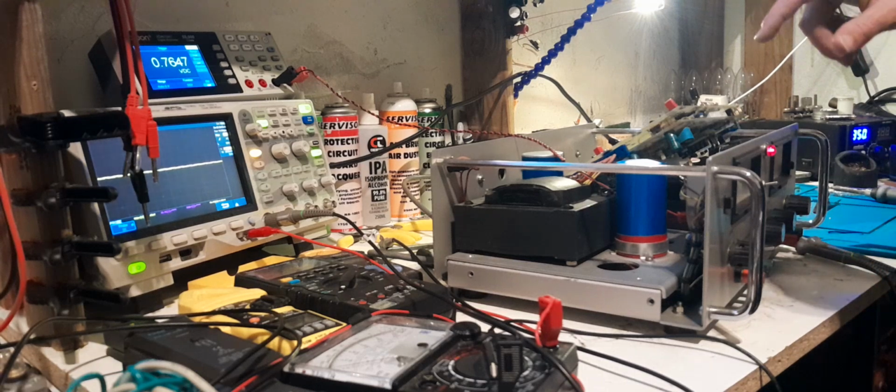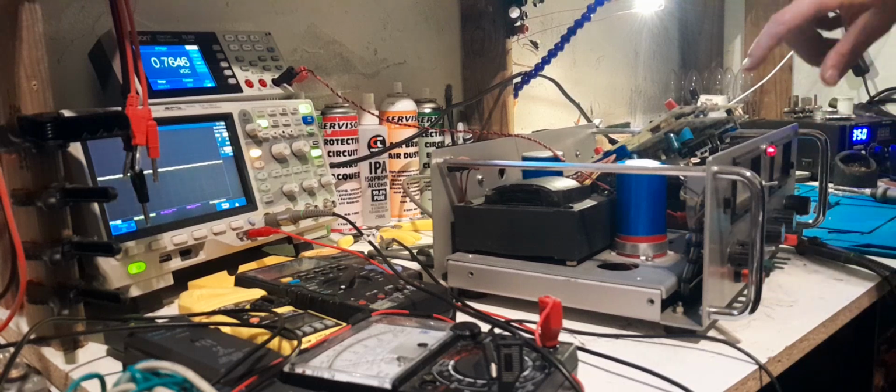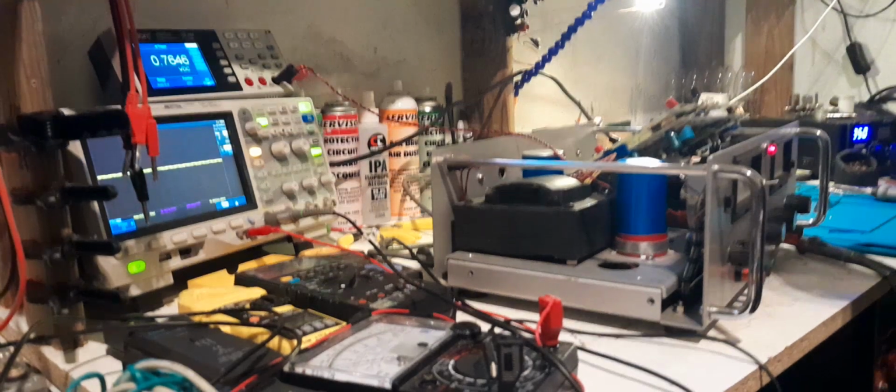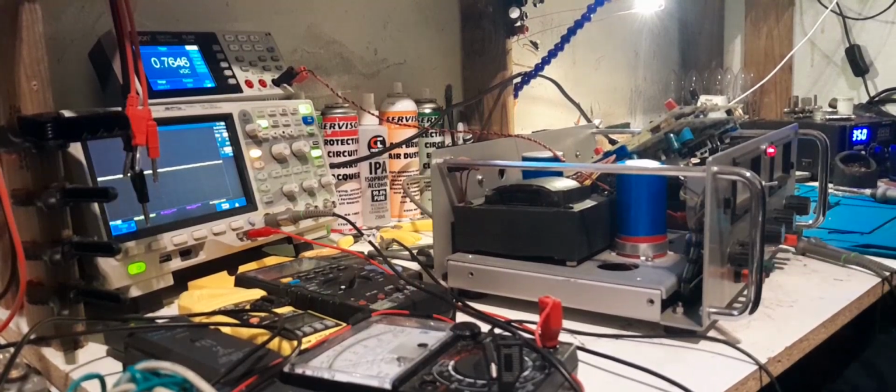One deducts the leakage current from the main op amp's sensed current from the shunt resistor, and then the 2 of those outputs go into another op amp that does some summing, or I can't remember how I've got it, but I think I've got 1, 2, 3, 4 op amps in my constant current circuit, but it's an insanely accurate circuit. So it's a bit different to this one. This has less accuracy on the current side. The constant voltage side is done really well.